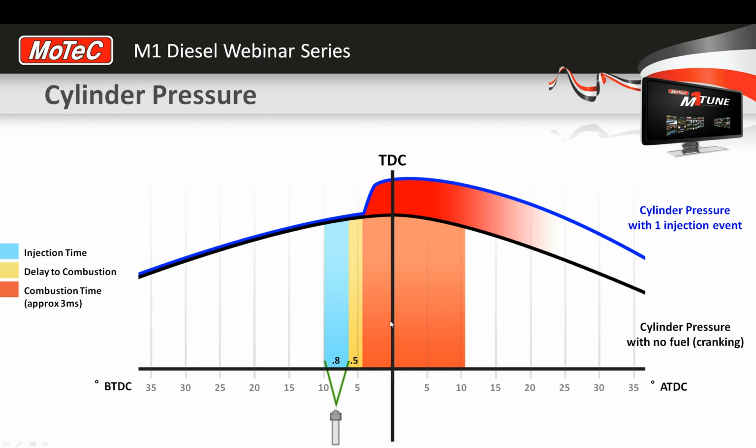Now the thing to remember about a diesel compared to a petrol is that the tiny droplets of fuel, the mist of fuel, is going in, and rather than a sweeping propagation of the flame that you get in a petrol when you light it in one location with the spark, a diesel tends to get thousands of little flame fronts, one for each droplet. So say 60 or 70%, could even be higher, I don't know exactly, of the fuel actually all burns at once.